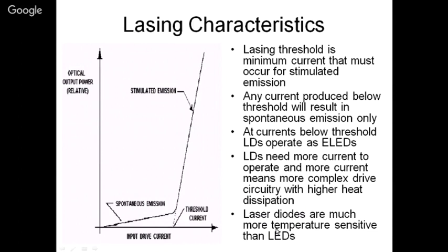Then laser diodes are also temperature sensitive. What happens is this threshold current increases if the laser is at a higher temperature. As the temperature increases because of the very functioning or illumination properties, or when you try to increase the current, heating also increases, and this increases the threshold further. So the laser can also get damaged because of this.